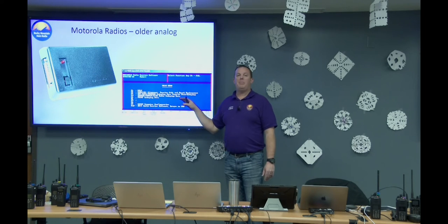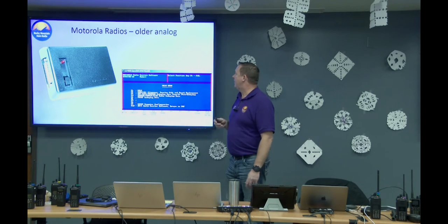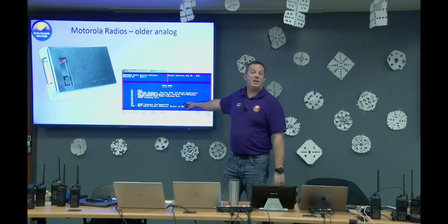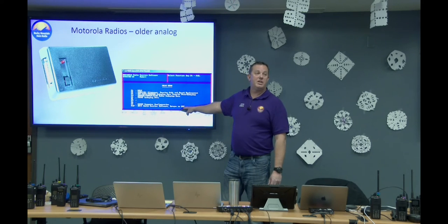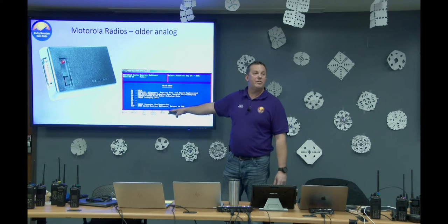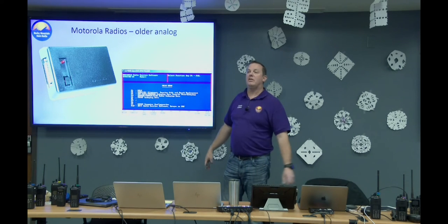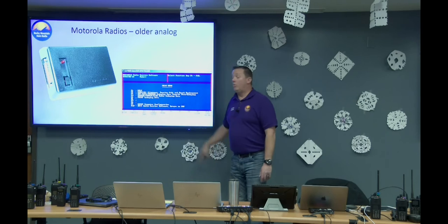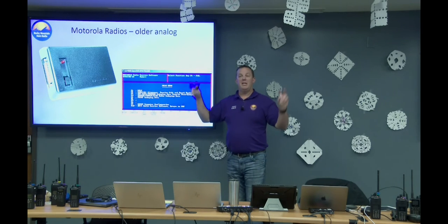And then the other caveat to the software for most of these radios is called RSS. It is Motorola property. It's long since discontinued. I've been informed that the copyrights have been dropped on this. So if you can find this, you can own it without being in violation of that. It's all DOS software. It all runs on DOS. So you either have to have true DOS or you have to have something like Windows 95, which has actually got DOS under the hood. It will not run in the emulated DOS stuff.